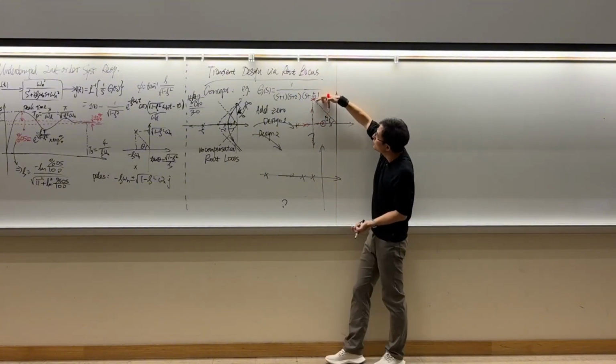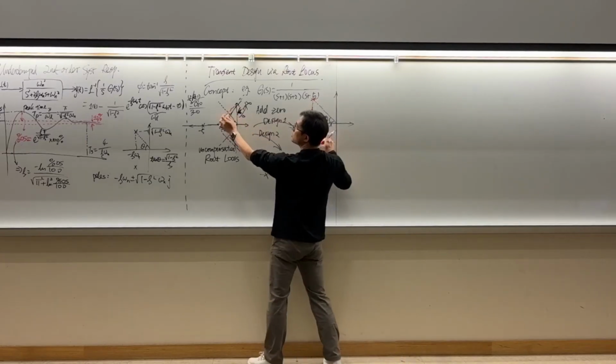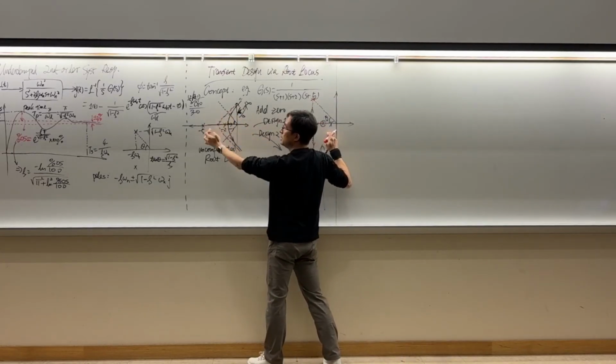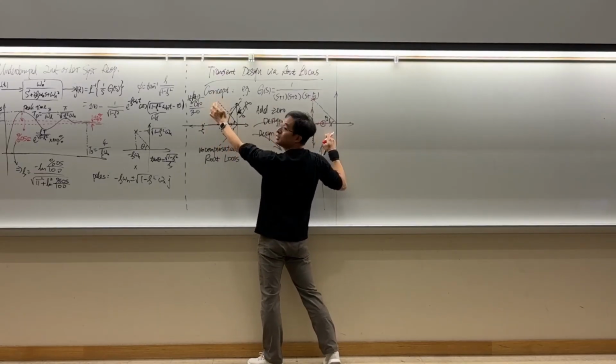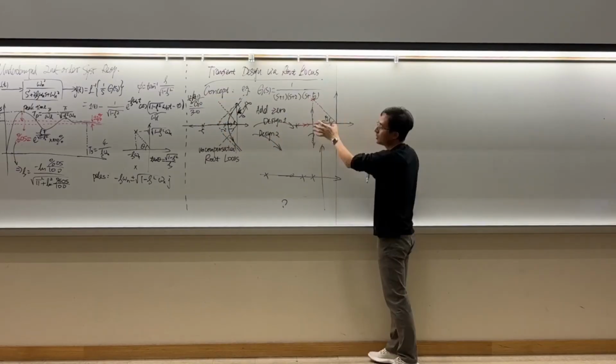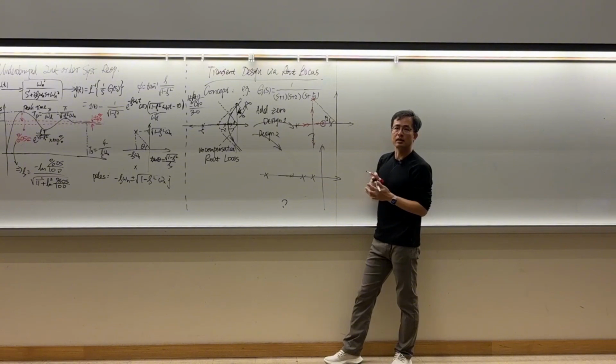The location of these is, compared with this, much more to the left, right? You shifted the root locus to be sitting over here. So if a closed loop pole is further to the left, what does that mean? Better stability, and the transient will be faster, right?